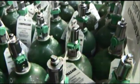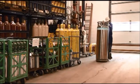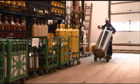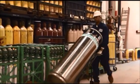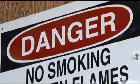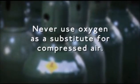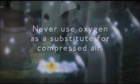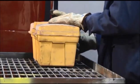There are several general precautions to be aware of for safe handling of liquid and gaseous oxygen. Do not store it in a confined space. Instead, store and use oxygen in well-ventilated areas and away from oil, grease, and other combustibles, and where the temperature won't exceed 125 degrees Fahrenheit. Keep ignition sources away from oxygen storage areas. And never, under any circumstances, use oxygen as a substitute for compressed air. People who handle oxygen must be trained to understand its properties and its safe handling procedures.